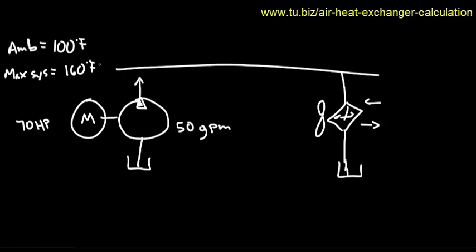So with this information over here, you have all the information that you need to calculate a heat exchanger. In this case, we're doing air. So that's why we have ambient temperature over here. If we are doing water, you need a different calculation that goes right into the plate heat exchanger, and you take into consideration water temperature and all that. But this is going to be with air. In this case, there's different methods on how to do it. The method that I prefer is taking in consideration the installed horsepower.